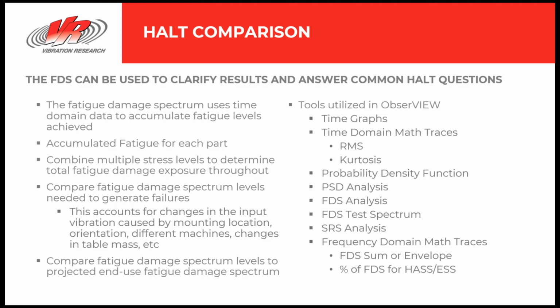The fatigue damage spectrum is, as we will see, a tool that allows us to get a relative damage per frequency bin accumulated over the entirety of the test. It is based on time domain data, so we're not using FFTs and averaging data together like we do with the PSD.